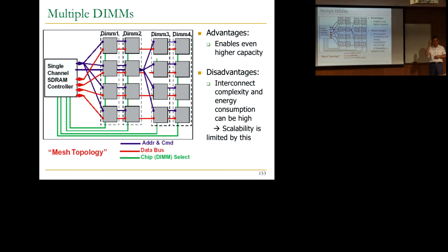Actually, FB-DIMM was developed, I think, maybe almost 20 years ago now, and that never took off, even though I think Intel was a big proponent of it at the time, partly because of this latency disparity. In order to access this far away DIMM, I think there were 8 of them, it took a lot of latency, and partly because they had these little buffer chips called advanced memory buffers on the DIMM that actually routed the request from one DIMM to another, and those consumed a lot of power at the time. That could have been optimized, I think, but they did consume a lot of power.